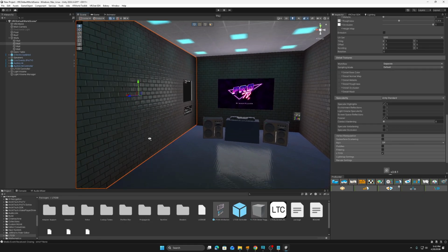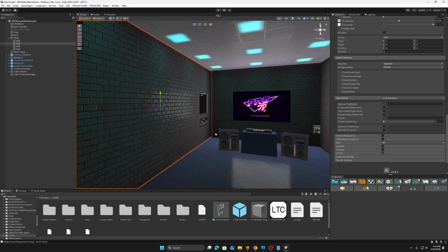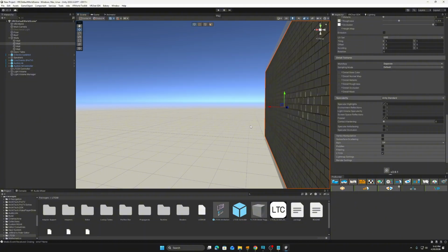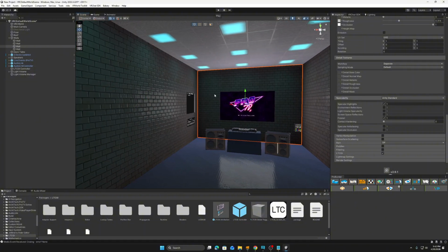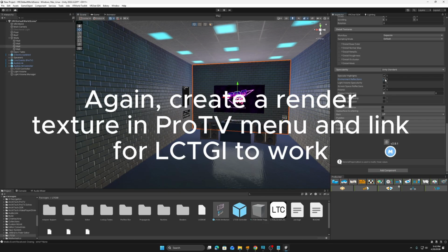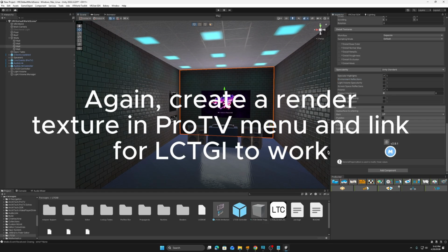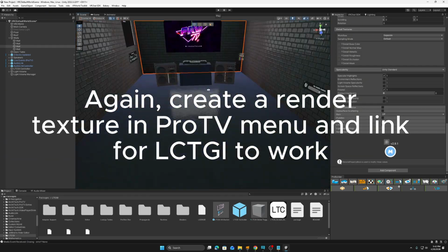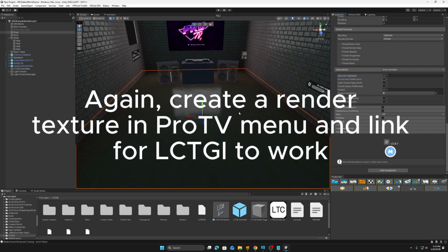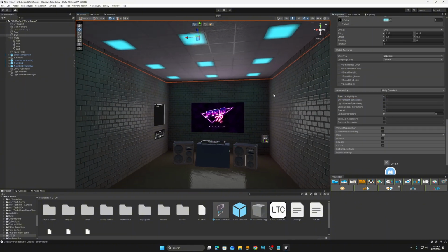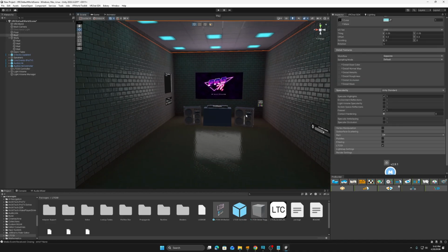One thing to do also, I just realized, make sure you turn off environment reflections for now, otherwise it's going to do the skybox. We can also just change the skybox too, but just for this case, go into the shader, scroll down and turn off the environment reflections. And if you have a directional light in the scene, make sure you turn off specular highlights, otherwise a big white dot will pop up somewhere. So we're going to do that for all of this, as well as this. And now we get this more natural dark look that we should.